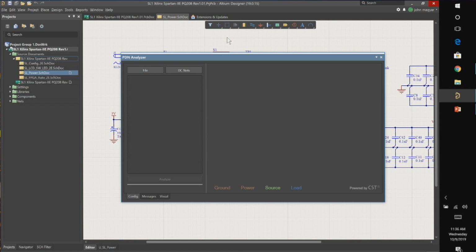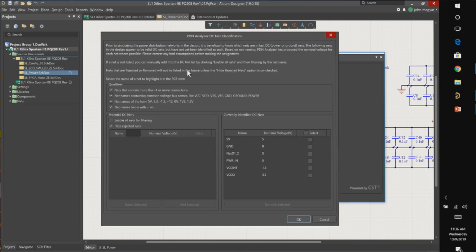So the first thing we want to do is define our power nets. And in this case, I can reverse back through this process. So if I actually sort of select these all and then remove them. When you first open up a design, your power signals are sometimes pretty obvious, and the tool will try to infer which ones they are. It doesn't always do a perfect job, but it's a big help. And generally, you get things lined up that end in V, or naturally GND or PWR. So these are all very common things that, when you first jump into a board and open this up, it'll detect these signals. You might have to go and add additional signals. So I could do that right now. So here's one that's typical that I know I'll need. It's a particular net.